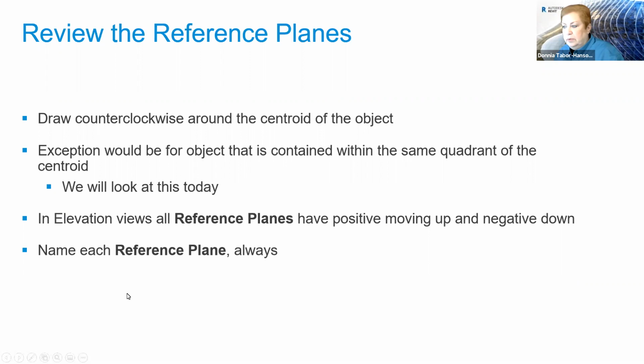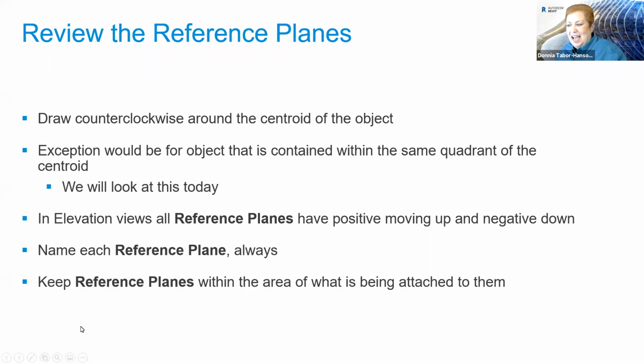And name each reference plane. Always name your reference planes. And keep the reference planes within the area where things are being attached to them. You don't want to open these families and find all the reference planes horizontal and all the reference planes vertical going all over the place, and you're like, I can't figure this out. Bring them into the areas that they're being used in. They don't need to go all over the place.